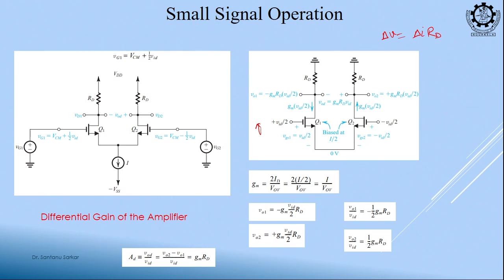You just do the calculation, na. V0 is equal to VDD minus ID RD. You take a derivative of this. Del V is equal to derivative of VDD, VDD is a constant, it is 0, and del ID by del V, this is termed as transconductance GM. So, we should get that, na,